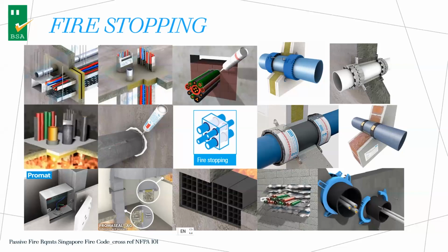So various forms of fire stopping are used to prevent the fire from spreading through this opening, whether the opening is created by cables or by combustible pipe. So we have systems that seal up the opening, or a fire collar that goes around the plastic pipe and crushes the pipe during a fire. So when we have more time, you can approach L'Aquatec to find out more about this kind of fire stopping.